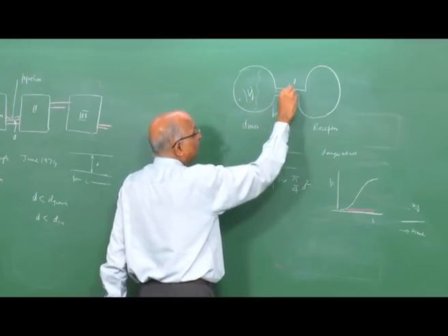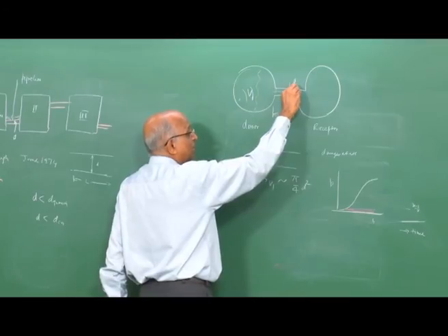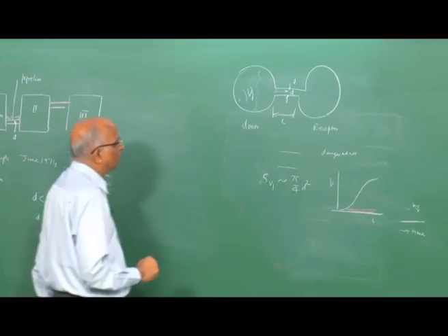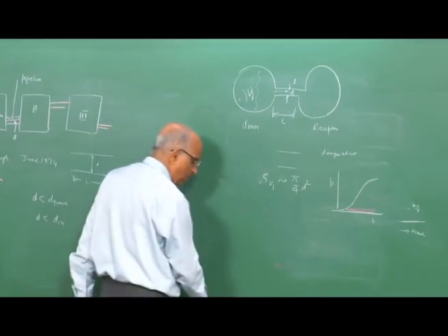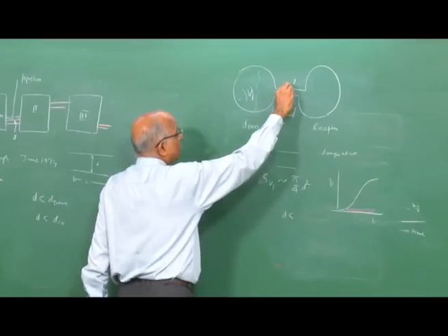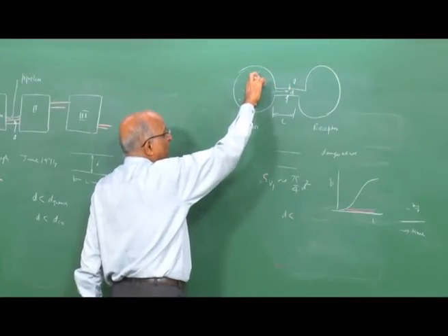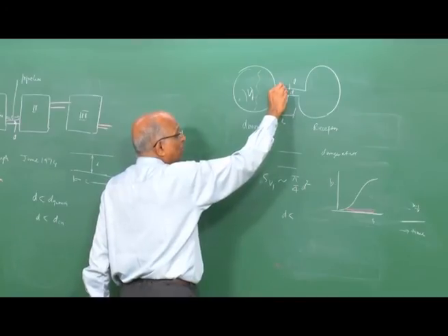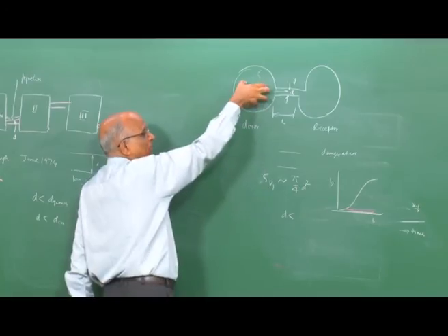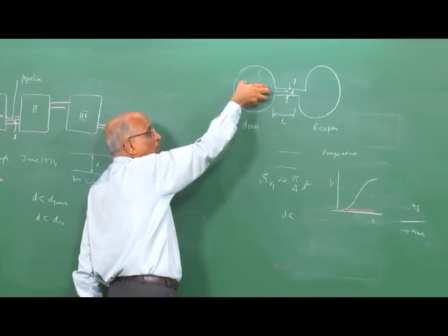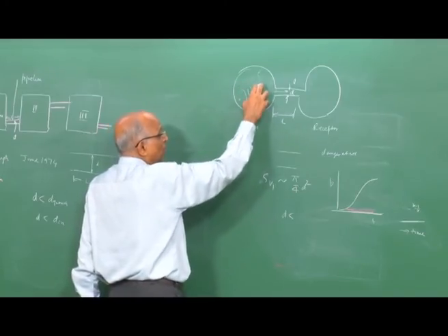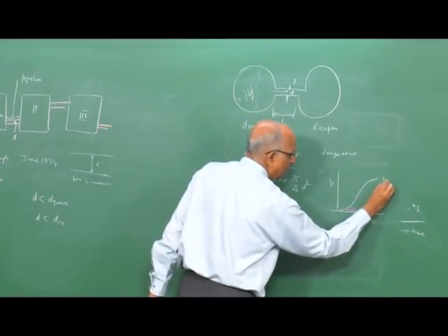Even if it is burnt, if the diameter is less than the quenching thickness, well, it quenches, nothing is going to happen, it's safe. But in practice it's not possible. In practice d, the diameter or the surface area, is going to be very much smaller than this, and therefore since the vent area is much smaller than the original cross-sectional area, this happens like a constant volume vessel or a constant volume reactor which is exploding, and in a constant volume explosion the maximum value of pressure is Pm,